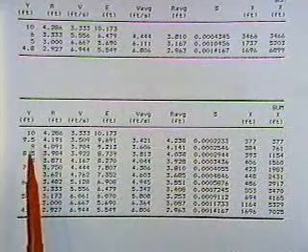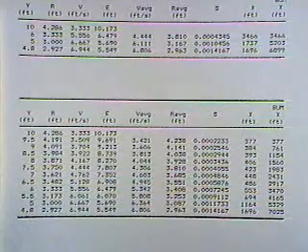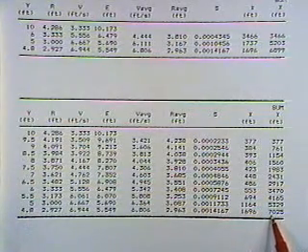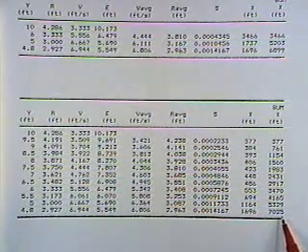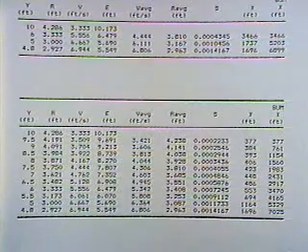And when you run it, all the computations all the way from a 10 foot depth to a 4.8 foot depth at a 1/2 foot step size, the horizontal distance came out to 7,025 feet, which is pretty close to that 6,901 I got before. So basically, I'm not too sensitive to step size, as long as it's relatively small.